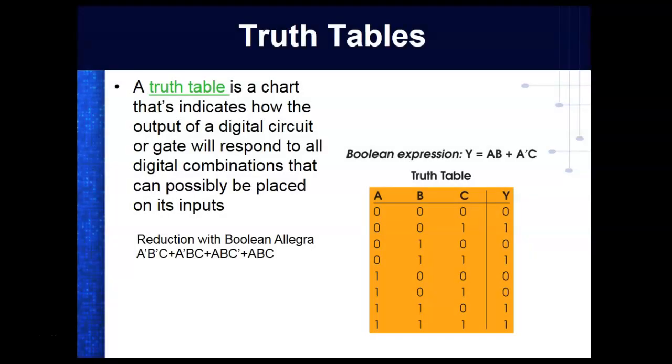So truth table, and this is what we're talking about. This is the truth table. So what you have to do: 1, 2, 3, it's got 3 inputs. So it means I'd have to have 2 to the third entries in my truth table, which would be 8. And all we do is we just count. That's where the truth table comes from.